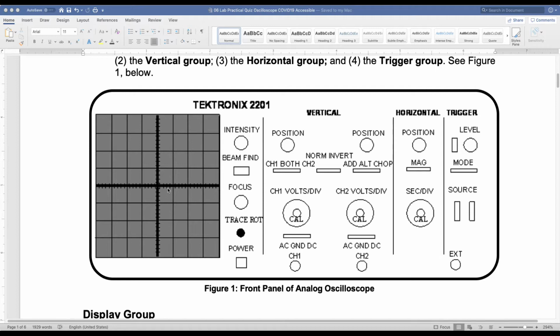And the reason why I say that is because the display, also called a trace of the signal, the voltage versus time that you see, the graph, is called a trace. That trace has a thickness to it. Its thickness is about half the spacing between the 2 closest divisions. So to say that you would be able to measure something to the 100th place just doesn't make sense to me.